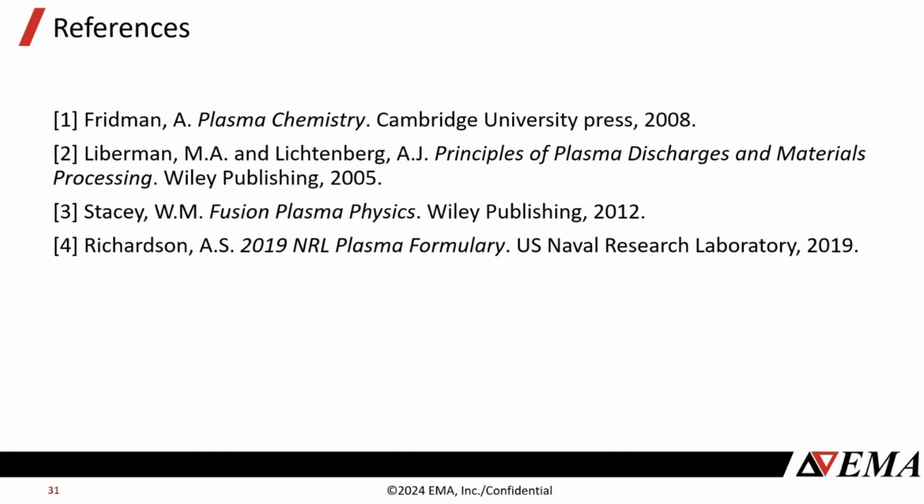The main difference here between an RF and a DC plasma is going to be how the conductivity is computed. In the RF case, you'll have a slightly lower plasma conductivity, which we are planning on adding support for in the future. But more importantly, when it comes to RF plasmas, what you really care about is not so much, well, you do care about the conductivity, but you care more about any sort of power reflection that can occur. And that is something that we can simulate, yes.